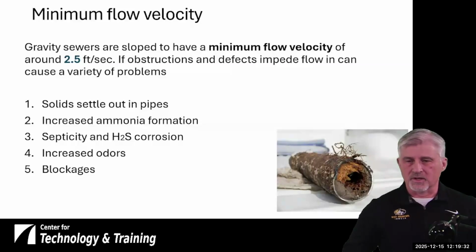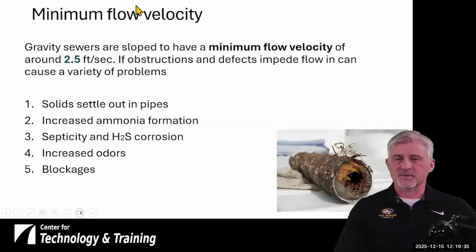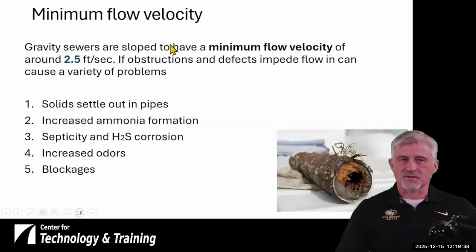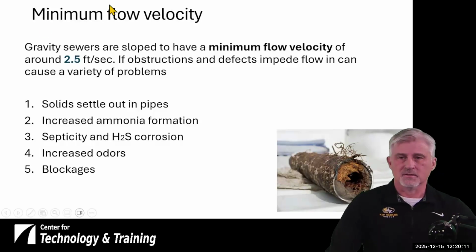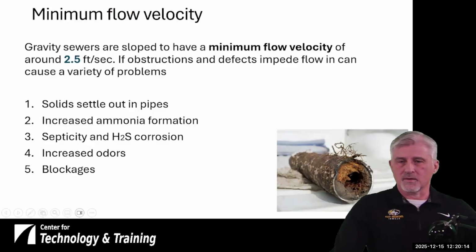and we also have increased ammonia formation. We have septicity and hydrogen sulfide corrosion. And septicity is a condition of wastewater where it becomes stagnant. I mentioned it a little before. Oxygen deprived, it's anaerobic, it's foul smelling. It's characterized by the breakdown of organic matter by bacteria, and it produces that hydrogen sulfide gas. It smells like rotten eggs, and it corrodes the pipes. So we want to avoid that. The increased odors can be a result of not having enough flow. And then we can also get blockages and stop the flow of the water in the pipe.